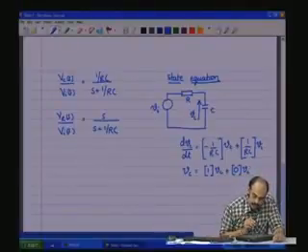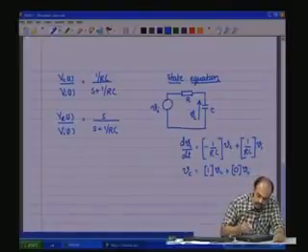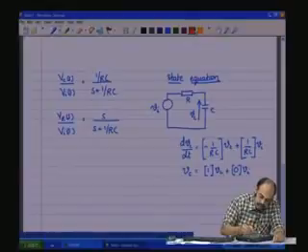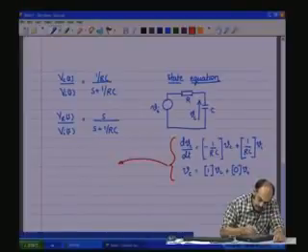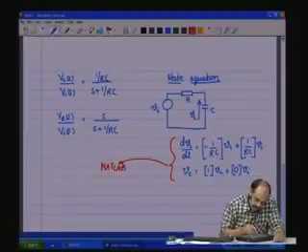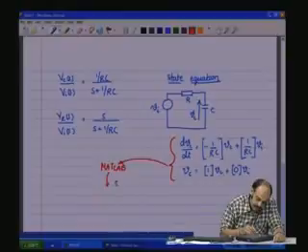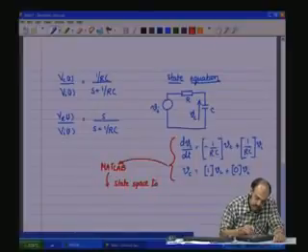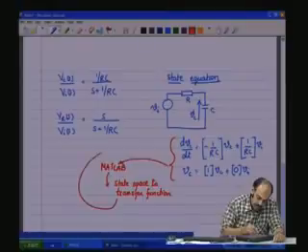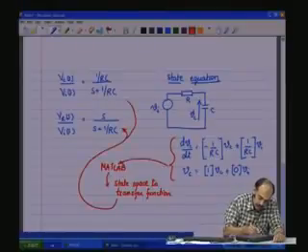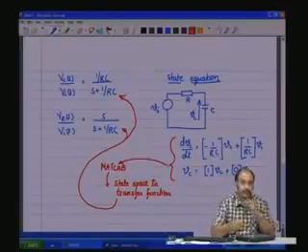Now, we shall do a small process, that is, we take this state equation model, input it to MATLAB, so in MATLAB let us make a conversion, state space to transfer function model, and obtain these models depending upon what we want to give as the output variable that we want to see.